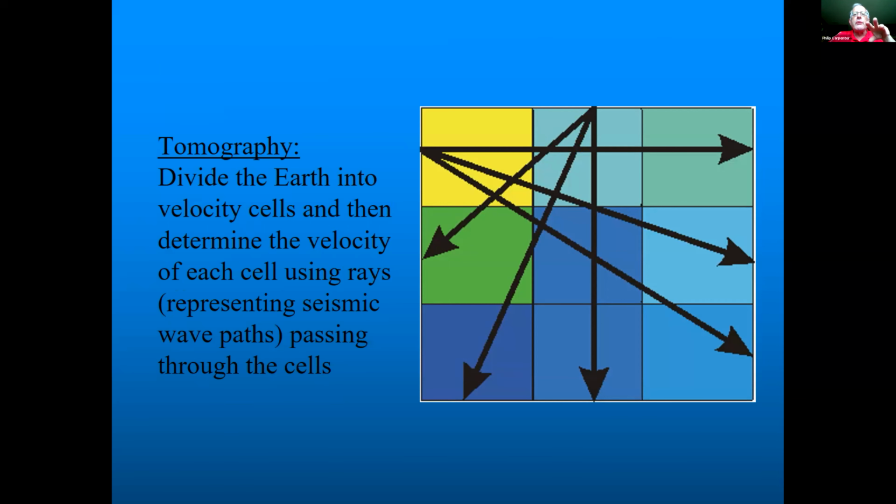The velocity depends on the shear modulus and the bulk modulus, which is really important in landfills, especially these leachate recirculation landfills, because you're getting deterioration of the waste over time. That changes the shear modulus and the bulk modulus, which can affect the dynamic properties of the landfill. And there have been cases of collapses, slope failure, and things like that in landfills because of that.